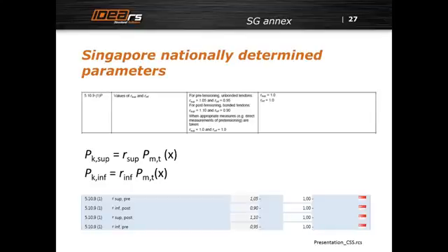Our committee in Czech Republic did not do it, and I think it's a little bit impractical, I would say, to design the structure for a scatter of 20% of pre-stressing force. It really makes a problem, and if you measure the level of pre-stressing force in the pre-stressing tendons and record it during pre-stressing, then I think it is not necessary.